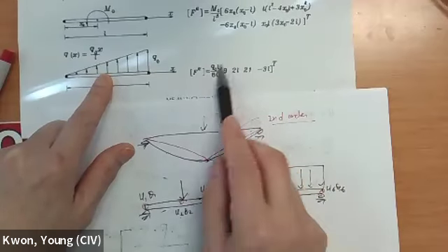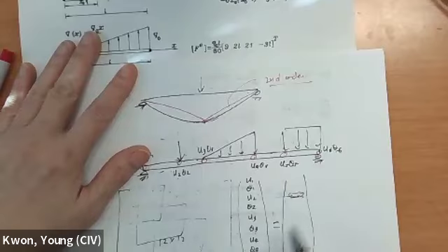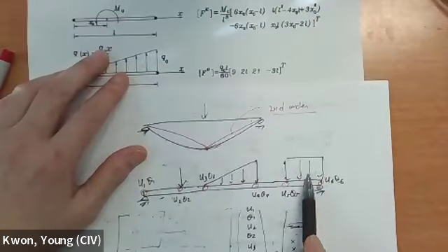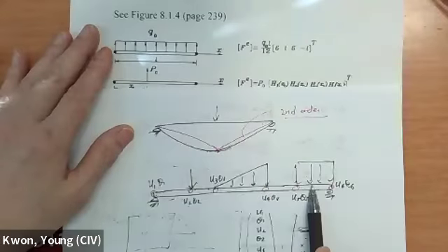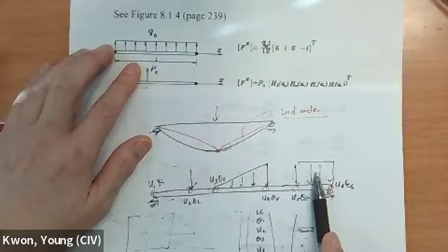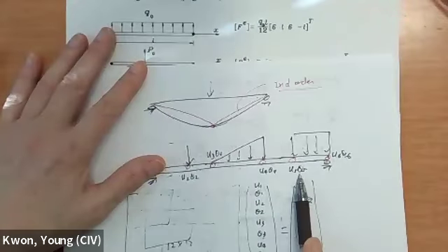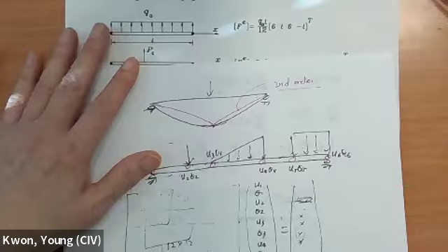This 4 by 1 column vector goes into U sub 3 to U sub 4, so it is added to here. Then the last one is this, again with a minus sign because the loading is in the opposite direction, and that goes to U5, theta 5, U6, theta 6, so it is added into here.